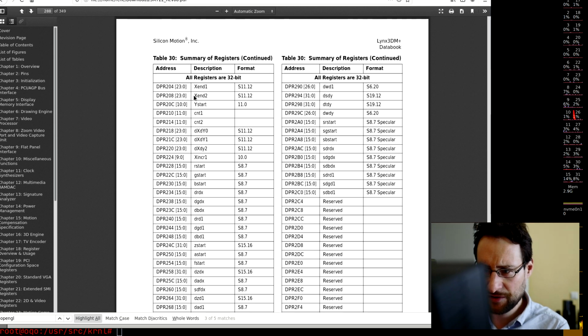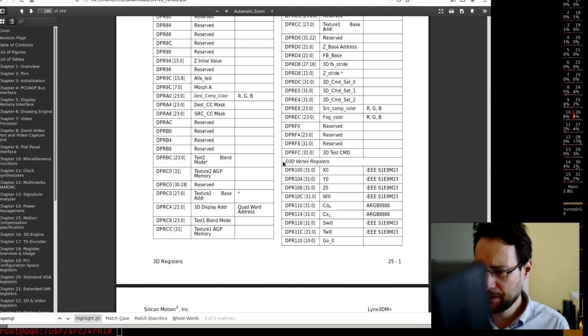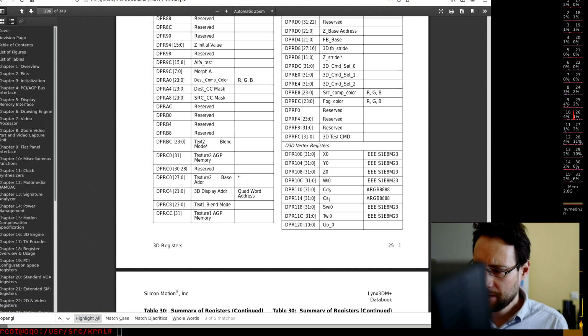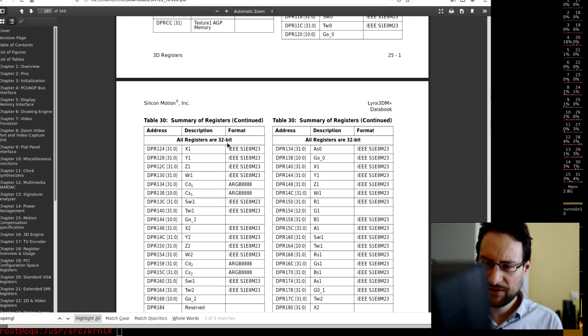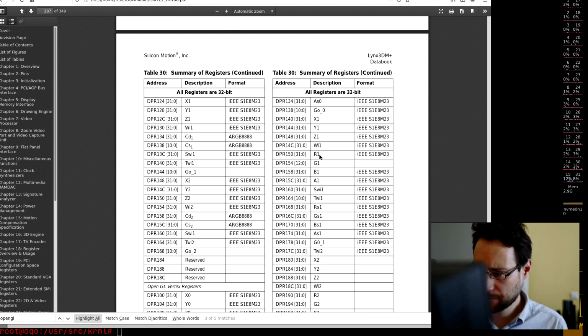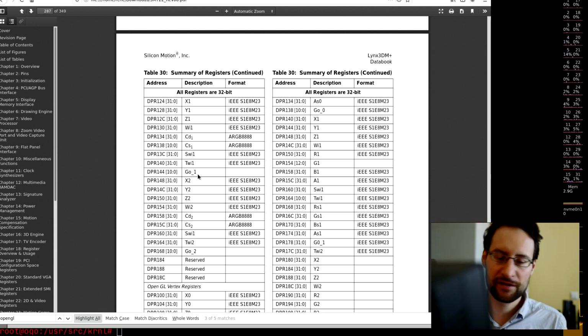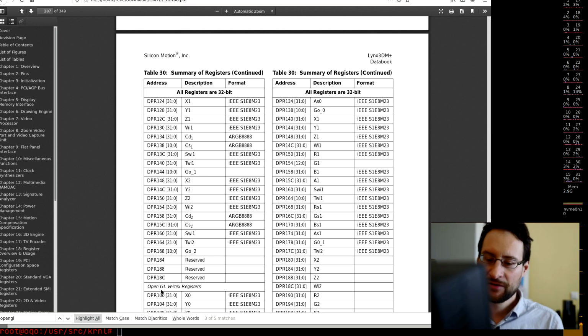Here is like Direct3D and OpenGL vertex and 3D. This is also not really explained. Only after some thinking I figured, these are the same registers in memory, and depending on whether you enable Direct3D or OpenGL, these vertex registers are at a slightly different location, and the biggest difference is for OpenGL the colors have floating point formats here, RGBA, and for Direct3D this is why these registers move a little bit. So I thought maybe this Direct3D stuff is broken. I already switched it to OpenGL, changed all my code to use OpenGL registers. It also doesn't work. So yeah.